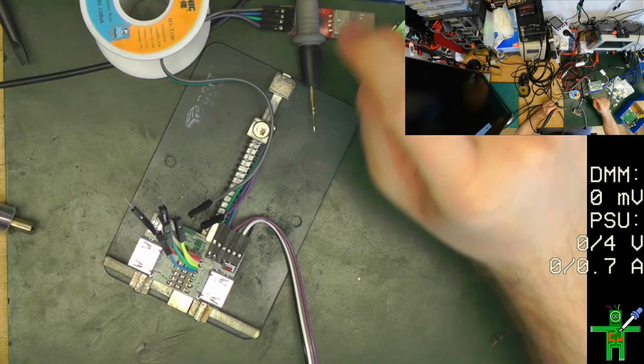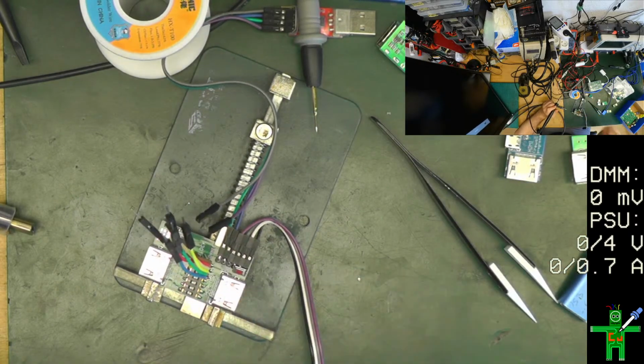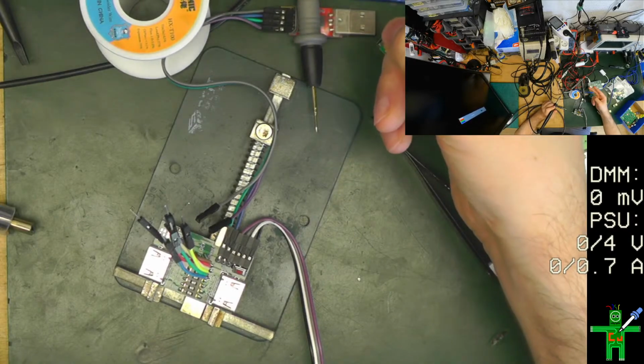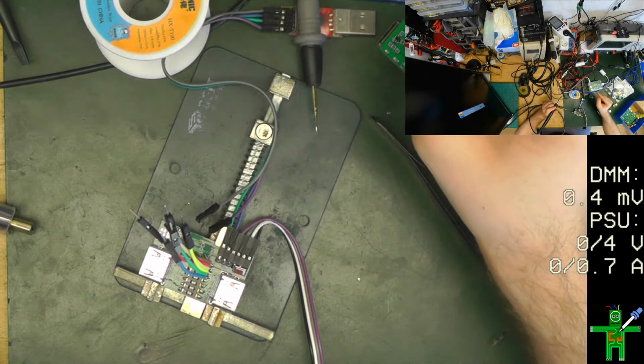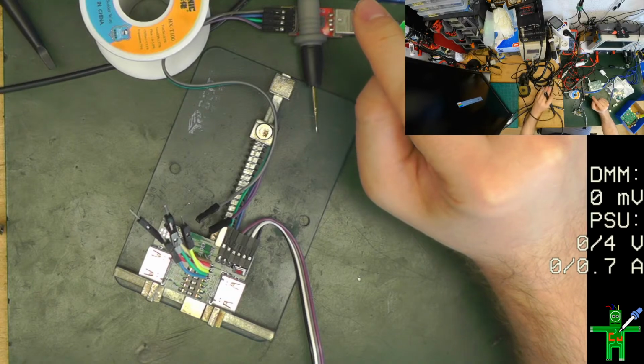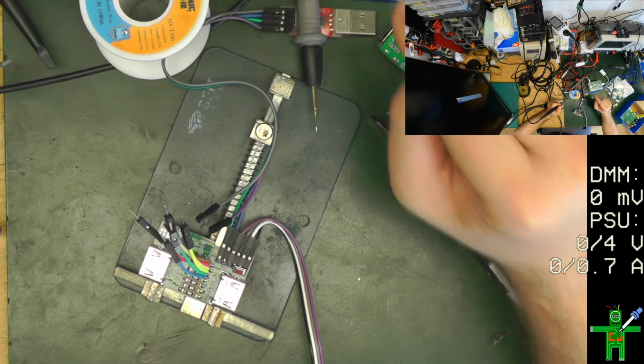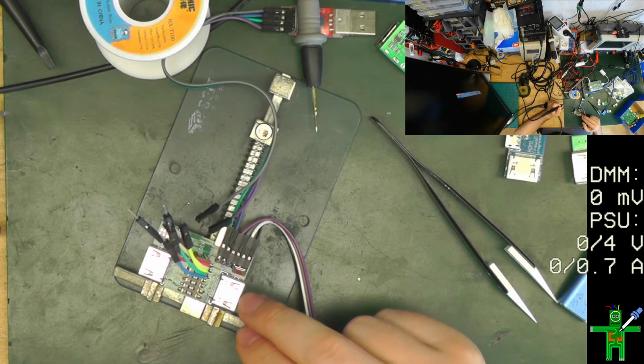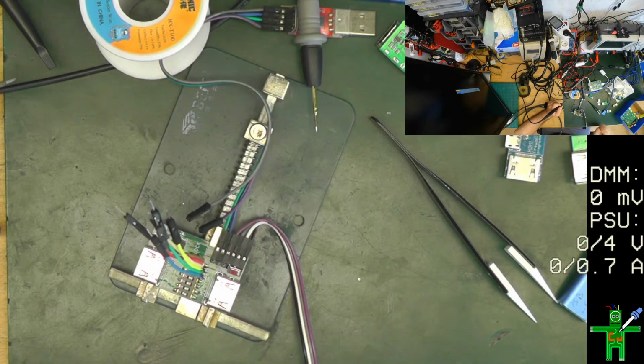What's good is that video transfer works, so my high-speed signaling is okay. It's not perfect though. The differential pairs are length matched within the pair, but not across the pairs. I didn't read up on it, I don't know if it is a must that they be length matched across the pairs. I will still fix that for the next version. I think it works. I tested it on the screen, and HD works without a problem. It might be an issue with 4K. I don't have any 4K monitor, so I cannot test it.